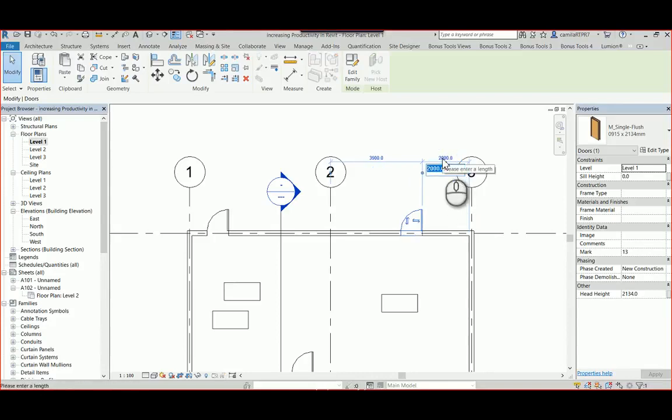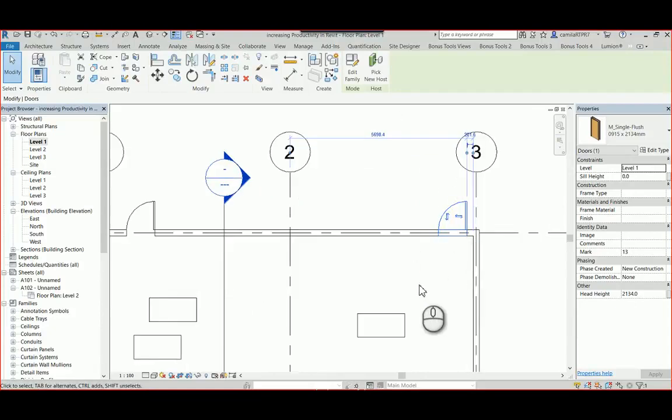You can also add calculations if you want, and Revit will do the calculations for you. So just an example here, and you can also combine different dimension units. Revit does the calculation for you. In this case, my file is in millimeters, so I didn't need to type the 200 millimeters. But if you type both dimensions, 200 millimeters plus 1/16 of an inch, a warning will pop up saying that it's inconsistent units. So if the file is in millimeters, it will assume the non-specified measurement is in millimeters.